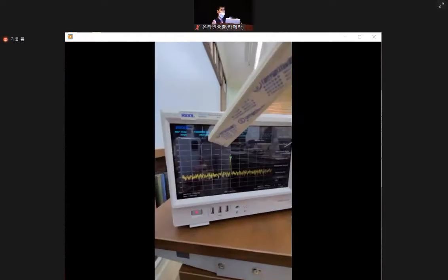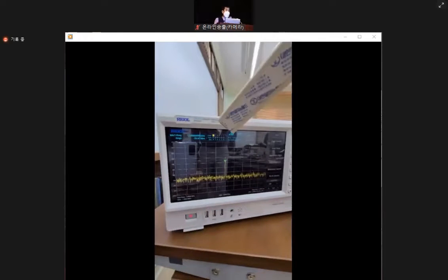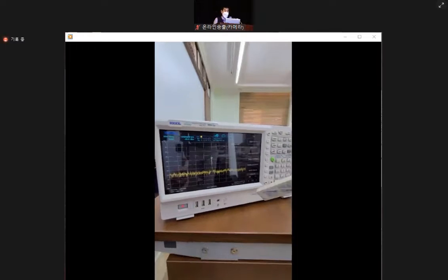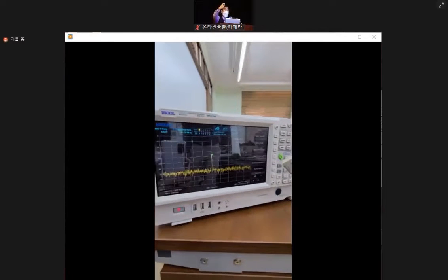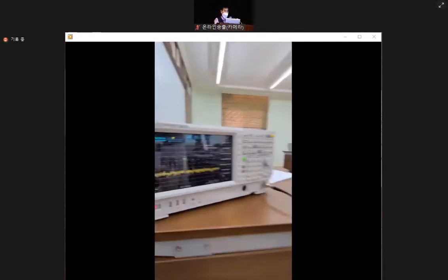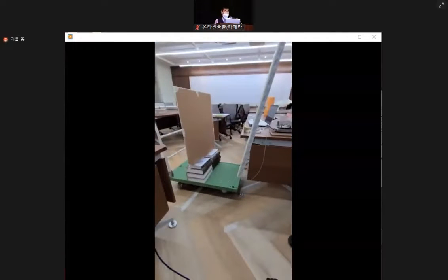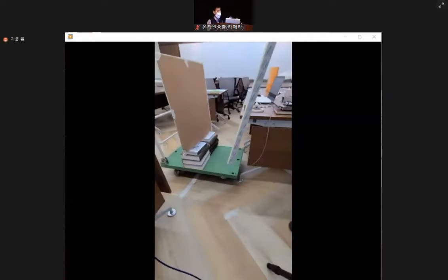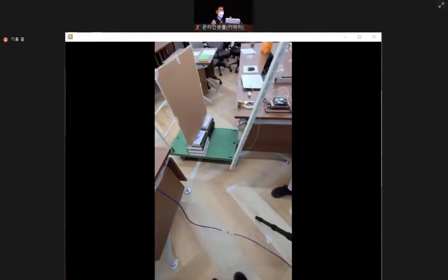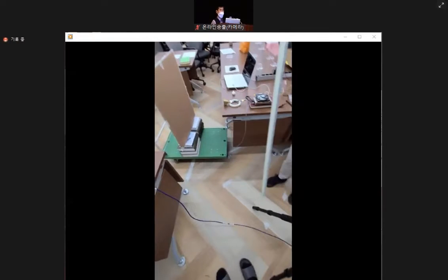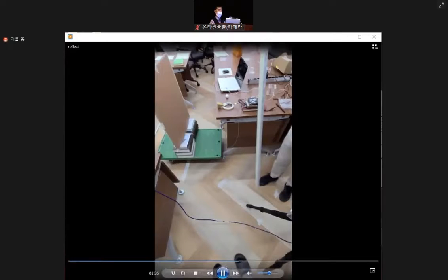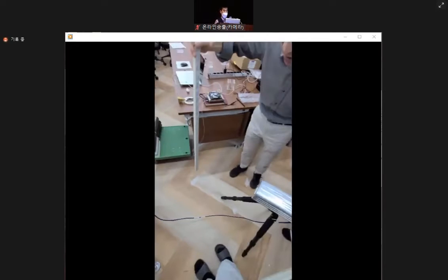Here we will read the strength. This spectrum analyzer is attached through the cable to the probe. dBm. You can see the green marker there that tells you the strength. The signal strength has been lower than before. Why? At the same angular position, but the distance has increased.